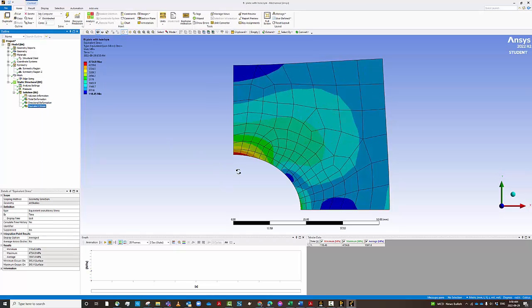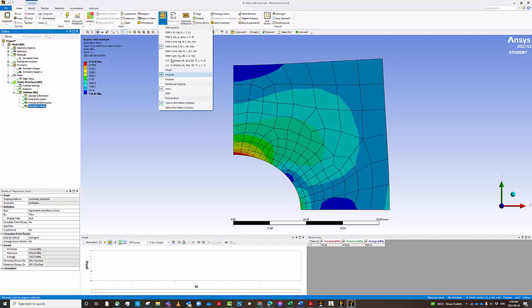So again, what I want you to do now, based on this example, I want you to make sure, for example, if you select 10,000 nodes for the full element, you take 2,500, which is quarter, and see how the results compare. And also, I want you to play with the mesh and basically see how the results are dependent on the mesh.